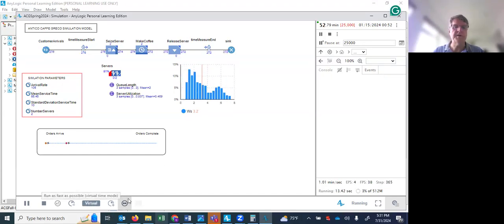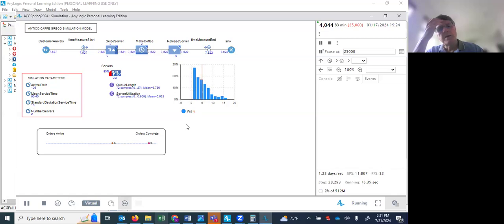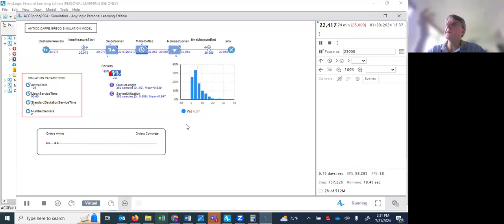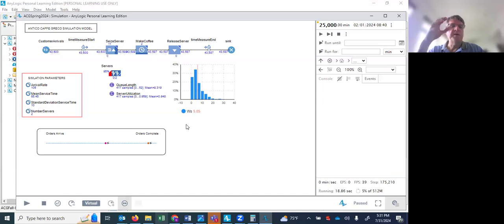Okay, click on this fast forward. I think in the queuing, we came back with something like 6 minutes. Now, this estimate is 5.85 minutes. I'll run this one again for you. Notice how my utilization is at 95%. According to this, this is an average across the hours of 94.8. I think this is sort of a short run average. Maybe it's just rounding the 94.8 up. I'm not quite sure what the difference between these two numbers is, but they're pretty close.